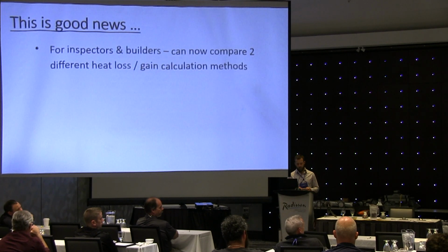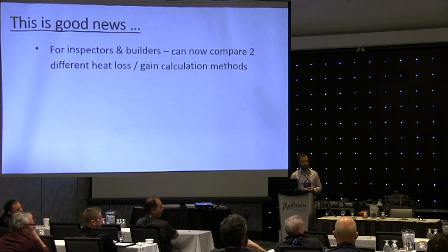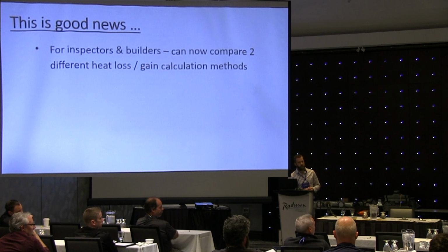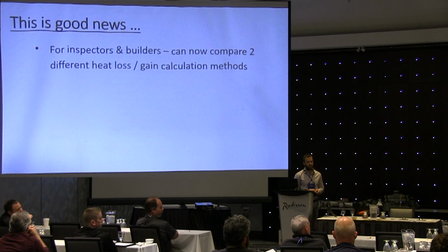And the third factor is that the public today has certain expectations of pickup. We are not building in pickup for this. We're building steady state load at design conditions in January. To give you an example, I live in a 1952 shack in Burnaby, 1,000 up, 1,000 down. We had 100,000 BTUs oil, went to 100,000 BTUs gas. Now I get 50 gas in it, and it runs half time on design condition. So that shack went in with 100, but its load is 25.